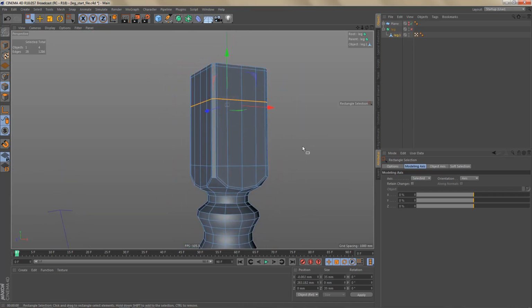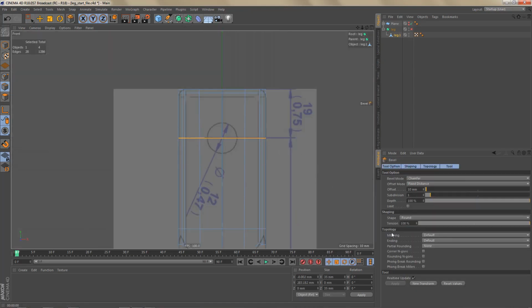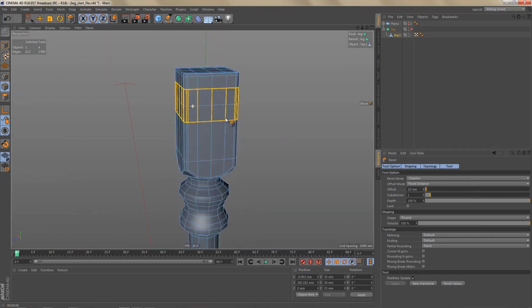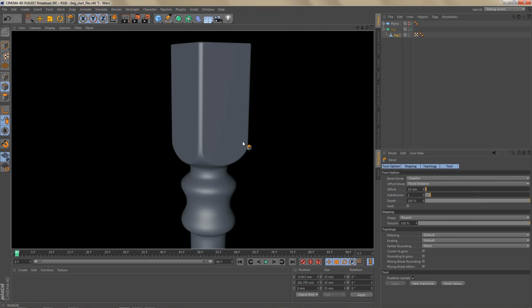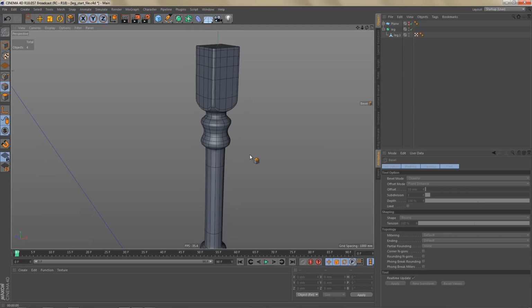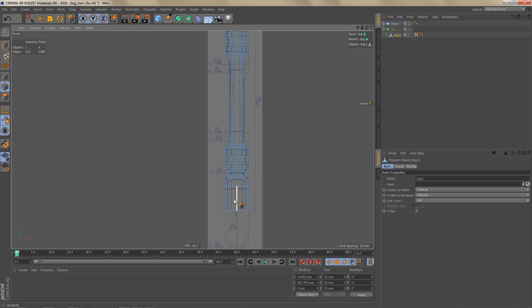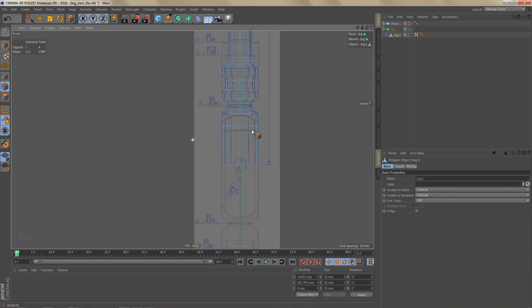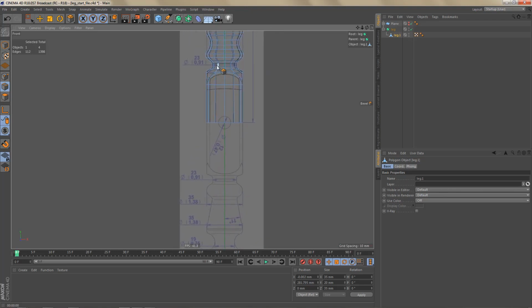And let's go ahead and bevel these edges here. Let's just make sure that I selected all of the edges. Same settings as before, 10 millimeters with one subdivision. So now we have the geometry that we need to create that hole later. Okay, so let's continue down here. Here at the bottom, at least part of the shape is the same as it is up here.